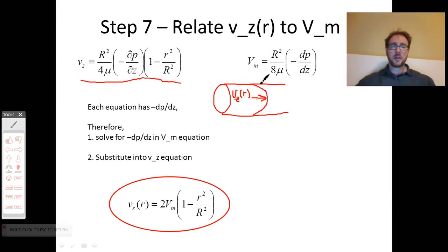I noted in the last video that we saw the same behavior for the temperature in a cylindrical fuel pellet, where the difference between the centerline fuel temperature and the temperature at the outside of a fuel pellet can be found. And then once you have the centerline temperature and the outer temperature of the fuel pellet, the average temperature of that entire cylindrical pellet is half of the maximum temperature, halfway between the fuel pellet temperature at the outside of the fuel and the fuel pellet temperature at the center line.